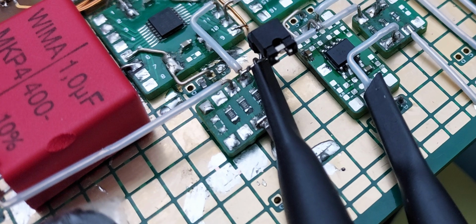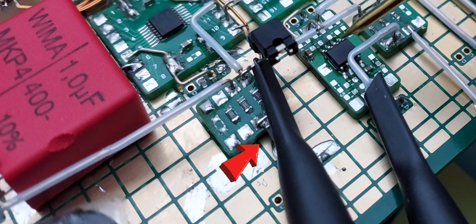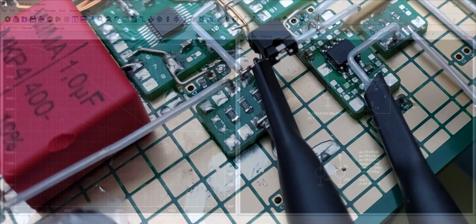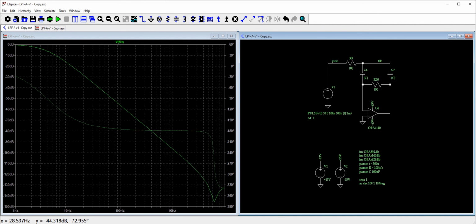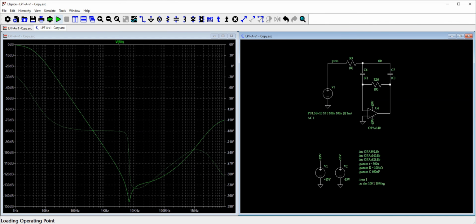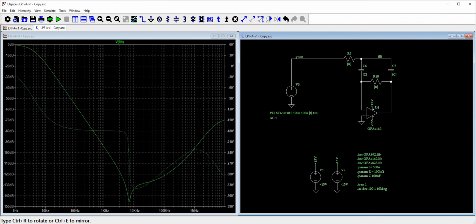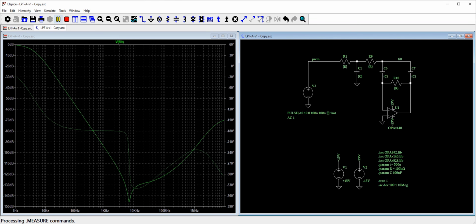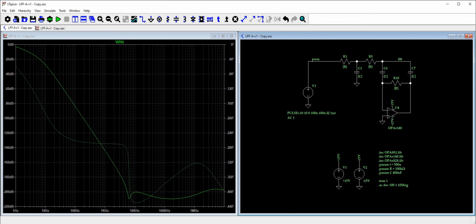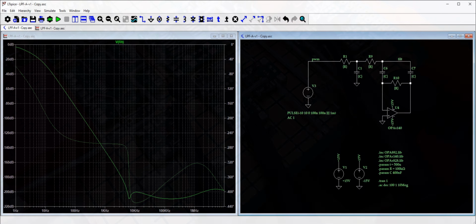There is one addition to the filter that is not part of the topology in the book, an RC pre-filter. This part of the Bode plot does not tell the whole story. At higher frequencies, the op-amp does not have enough output bandwidth to cancel out ripple. It turns inductive. This 20 decibel per decade decrease in attenuation causes the fast rising and falling edges from the analog switch to pass through the filter to the output. An additional RC filter cancels out the 20 dB slope and provides a perfect response.